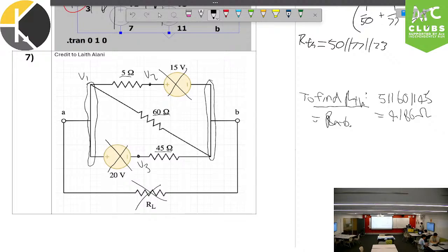V3. Now, after we've labeled these nodes, we can start trying to extract information from this circuit. If we treat this down here as ground, so this is 0 volts, this is the same as B, so B is equal to 0 volts right here. And so V2 will just be 15 volts because it's just above voltage sources.